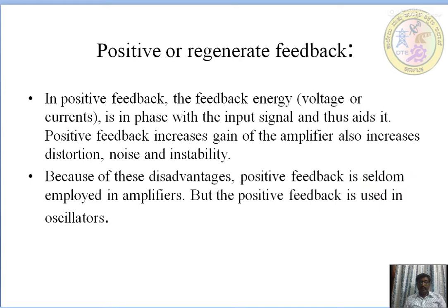Next, positive or regenerative feedback. In the previous slide we mentioned negative or degenerative feedback. In this, positive or regenerative feedback. In positive feedback, the feedback energy, that is voltage or current, is in phase with the input signal and thus aids it. Positive feedback increases the gain of the amplifier and also increases distortion, noise and instability. In negative feedback these were decreasing, and here they are increasing. Because of these disadvantages, positive feedback is seldom employed in amplifiers,